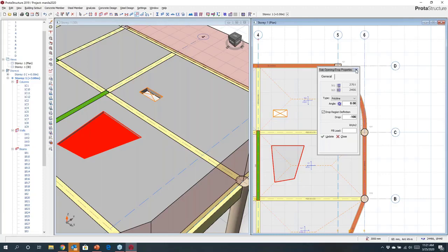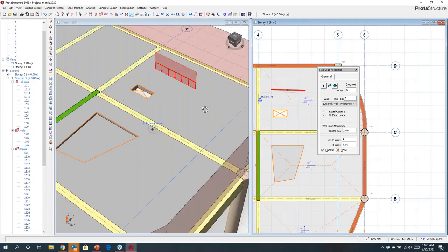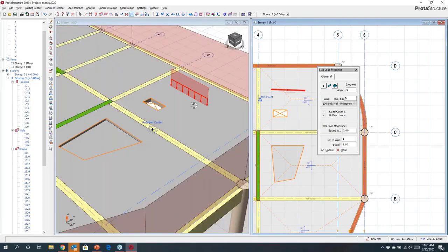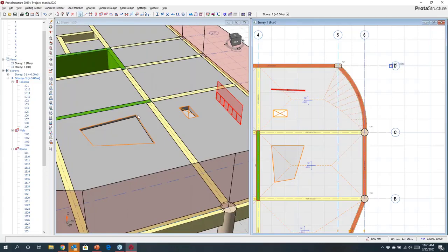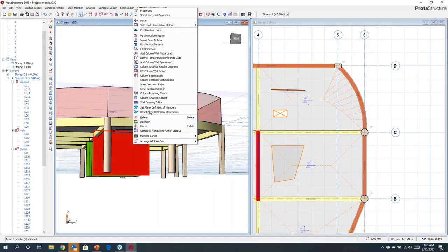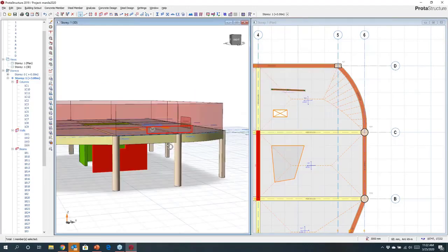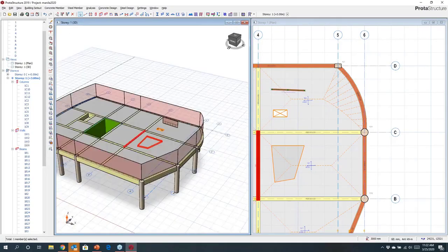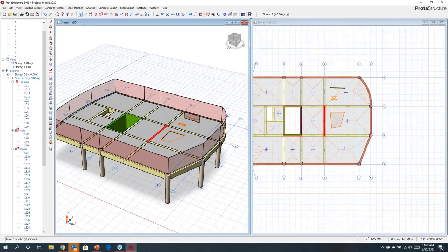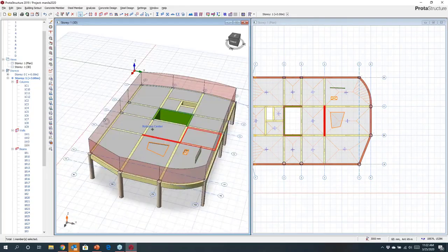Okay, there may be other things that you want to define on a slab. For example, again, you may have a brick wall or something just sitting on the slab. Okay, and whatever you create here, you can physically see. So you can see what's going on within the model there. Okay. There may be some other interesting things I'd like to do. Perhaps in my particular building, I've also got some openings, and I want to add an opening into a shear wall. Maybe it's for a window or a door. Okay, then I could easily come in and establish that in there as well. So you can see quite quickly there, I've just created a simple model. Okay, and I've just quickly developed that plan view.